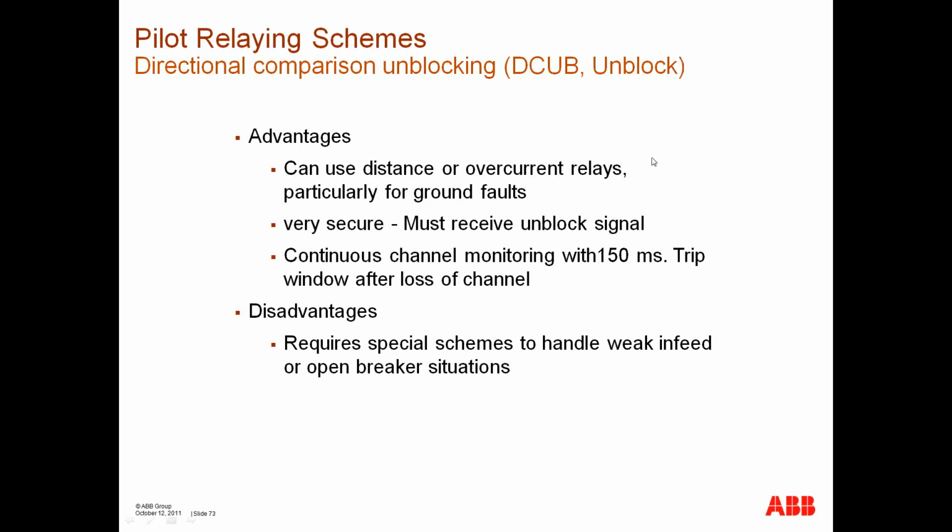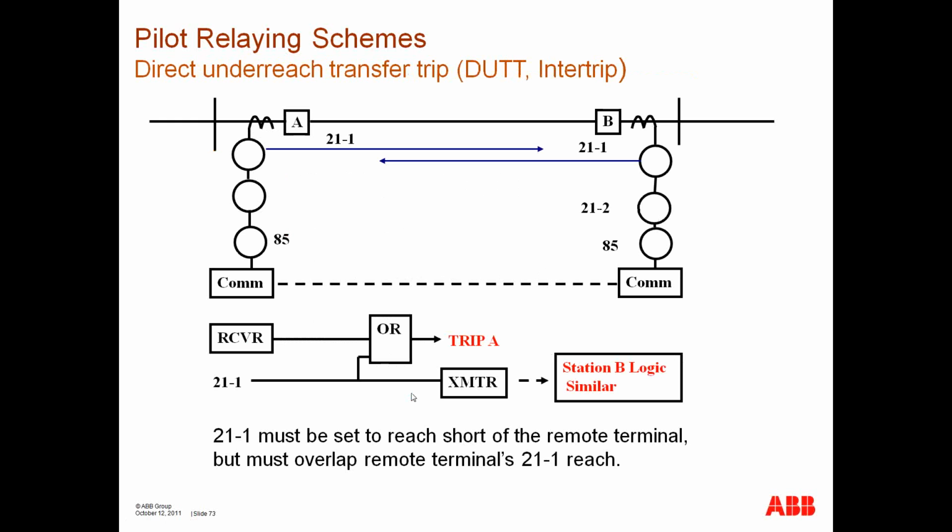The advantages: can use distance overcurrent relays. They're very secure. Continuous channel monitoring with 150 milliseconds trip window after loss of channel. Disadvantages: require special schemes to handle weak in-feed and open breaker situations. Well, that's not so much of a disadvantage, but they're good systems.